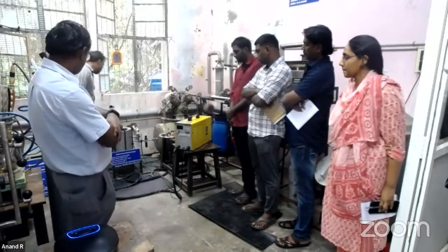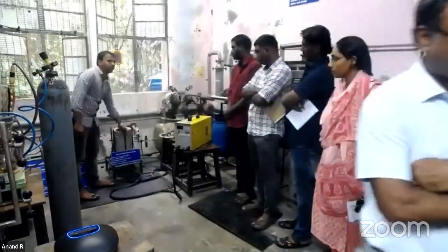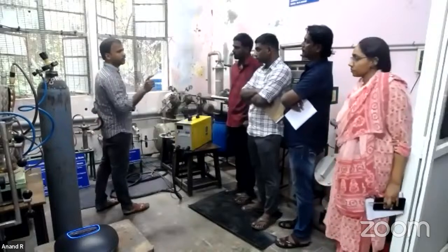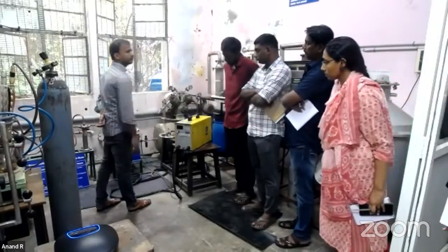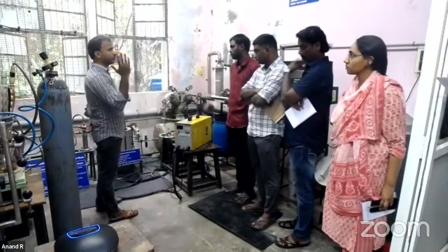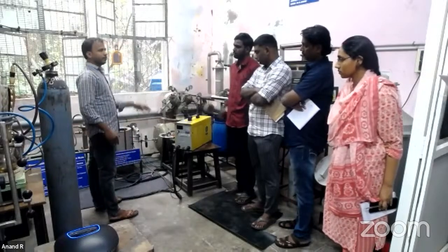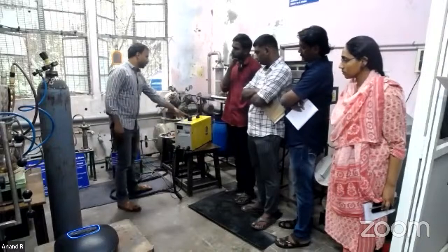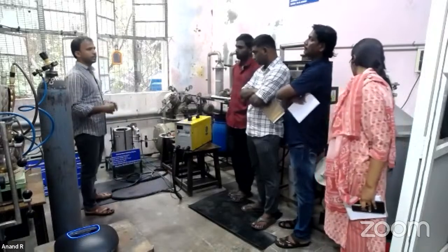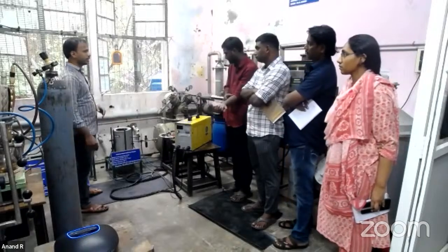So here, if you look at the reactor, this is the high voltage probe, this is the ground probe. Between the high voltage and ground probe, we are maintaining the voltage and the current. In the cold plasma case, we can adjust the voltage, but here we can adjust the current. Here we can give a current from 20 amps to 70 amps. This range may vary, 20 to 120, 20 to 180, depending on our scalability or requirement. We may give different capacity plasma generators. So now we saw a simple demo of how to generate hot plasma with this setup.